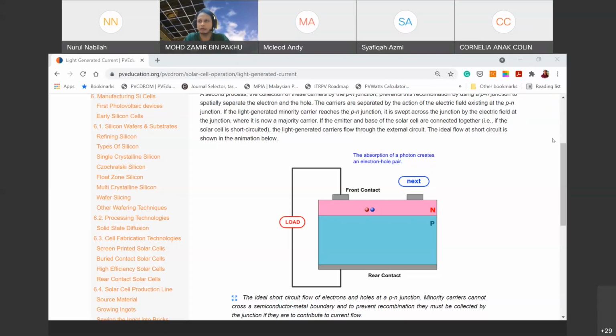On the other hand, if the photon energy is less than the band gap, the photon will be passing through the silicon without being absorbed, okay? And then it will just leak through the back of the solar cell, unabsorbed, okay? So in this case, since the E_ph is more than or equal to, the light will be absorbed.